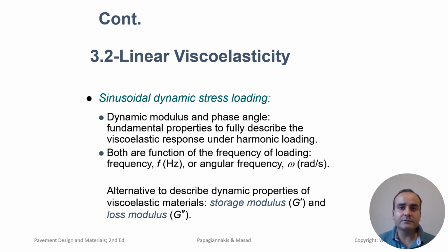The storage modulus represents the elastic component of the material's response to dynamic loading. It indicates how much energy is stored in the material during deformation and is subsequently recovered when the load is removed. The loss modulus represents the viscous component of the material's response to dynamic loading. It measures how much energy is dissipated as heat during each loading cycle, indicating the flow or viscous behavior of the material.